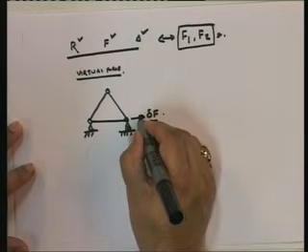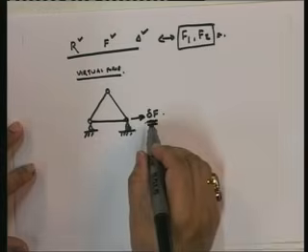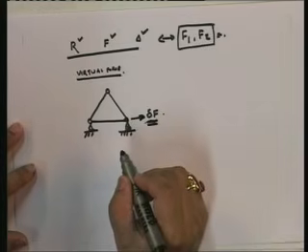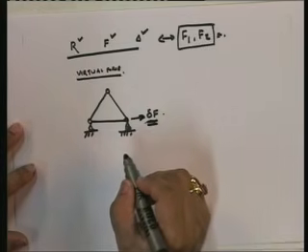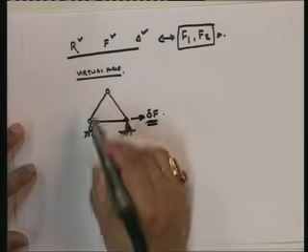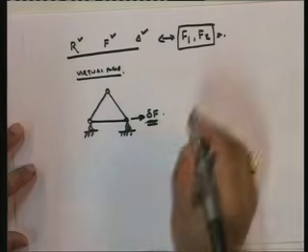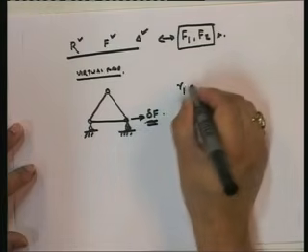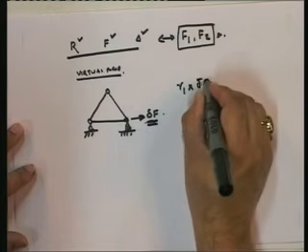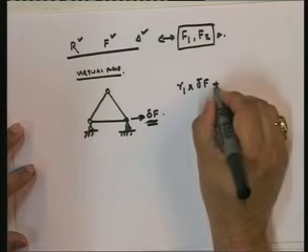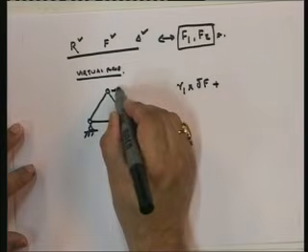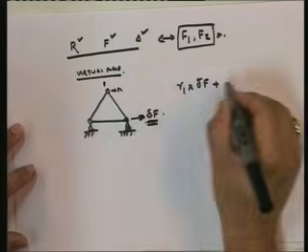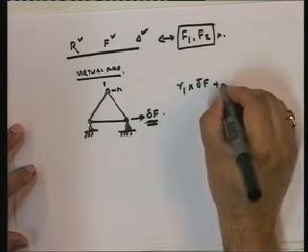So I only need to find out this displacement, and therefore if you look at the work done by all the external displacements, what is it? They are R1, the displacement that I am interested in, times delta F, plus, you see I have R2 and R3 over here, but they don't have any forces attached with them.